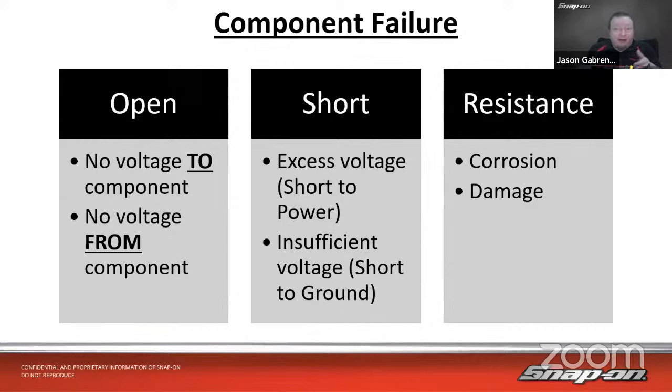Many components will have power, ground, and then a signal returned back to the computer. Maybe that signal's not making it back to the computer, right? So that's an open that way.